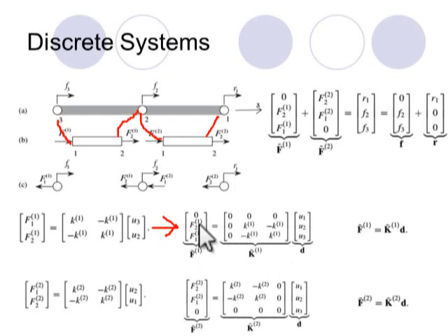Now I have the force coming from the second node. The force in the second node is equal to stiffness multiplied by the difference of the displacement between the second node and the third node in the global system. It is similar for the third node. Now look, I have a vector with 3 members.